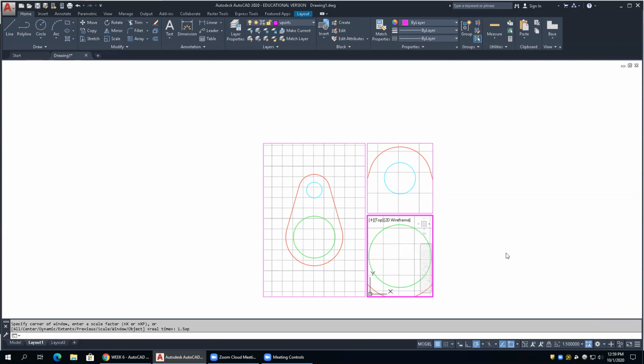All right, well, go see. Go to Z enter, get in here. Z enter. O for object. Select the blue object. No, you're not selecting it. You got to be in the viewport. Escape. Escape. Double click inside.